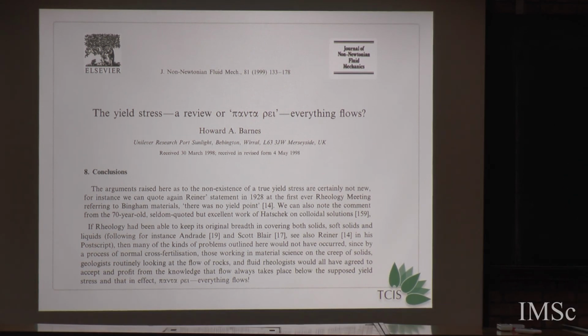So this is the controversy of whether a solid flows or not. I'm not saying that it's a secret, but it is something that should be pointed out more and more, because there are long review articles which show that actually there is no such thing as a yield stress, and the yield stress is strain rate dependent. So the lower the strain rate, the lower is the yield stress. It is a very smooth function.